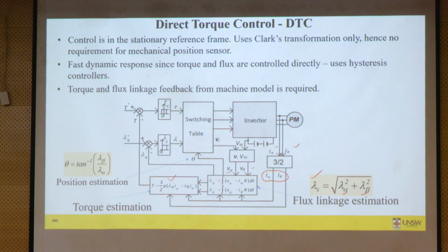Let's look at here. Okay, so we are finding that position theta here, this theta, right? It is the same way we will estimate it in position sensorless control. So to estimate theta, what we are doing is finding or integrating a voltage, right?